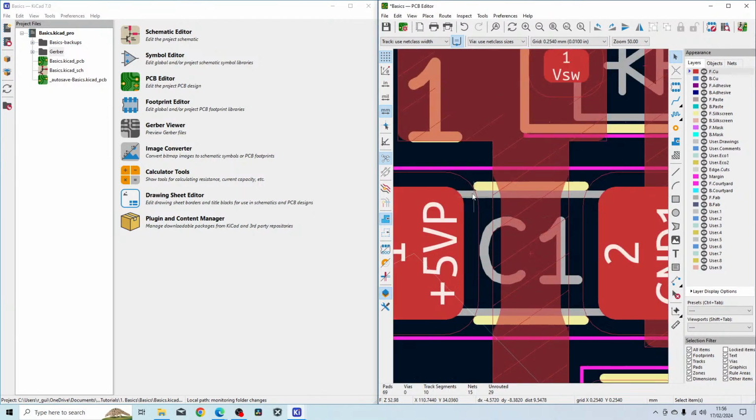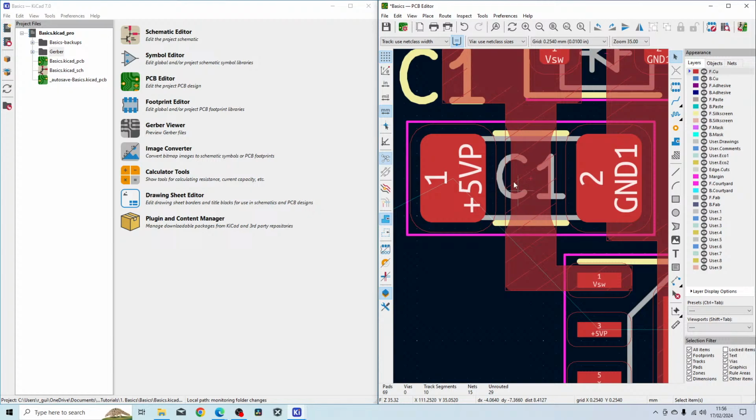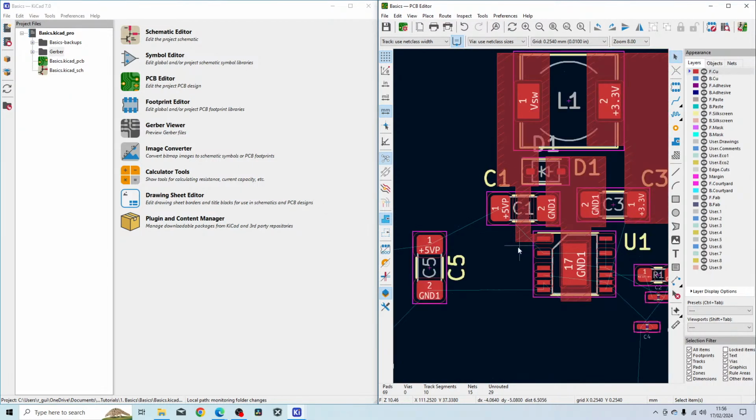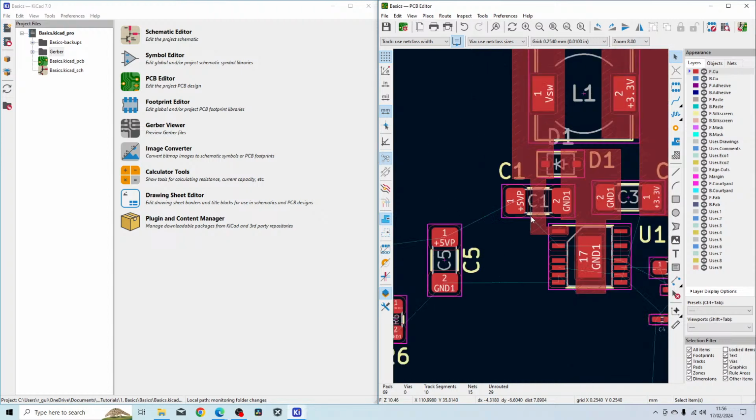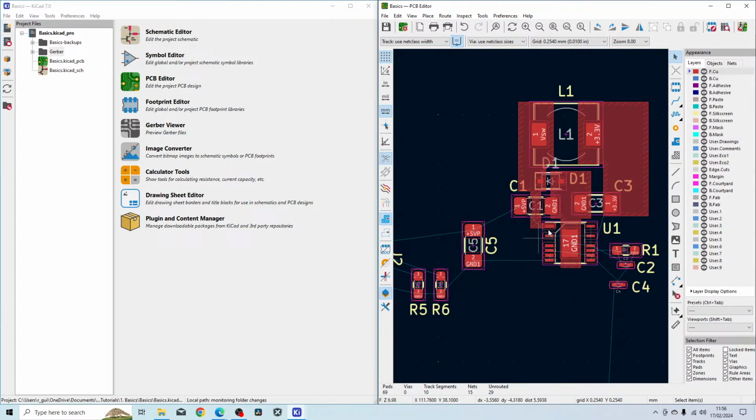So you can see we've got the copper pads here for the C1, and this layer automatically creates a gap clearance, or the required clearance, and that clearance is created from the rules that have been set up or predefined in KiCAD. What you want to do is make sure that the PCB manufacturer can meet that clearance. Otherwise, you might have problems.